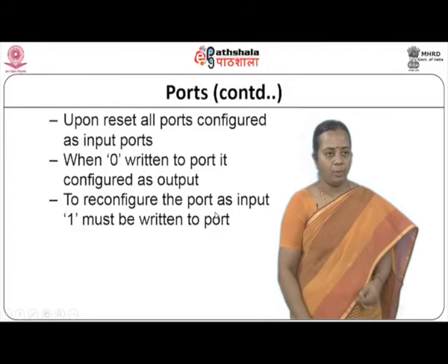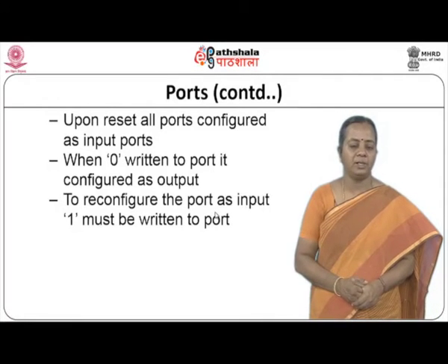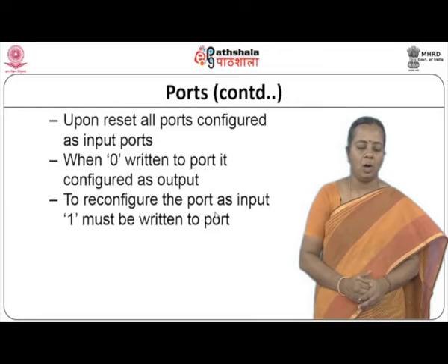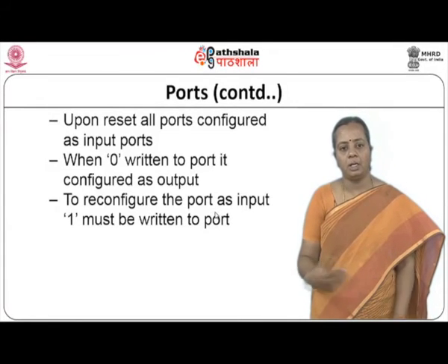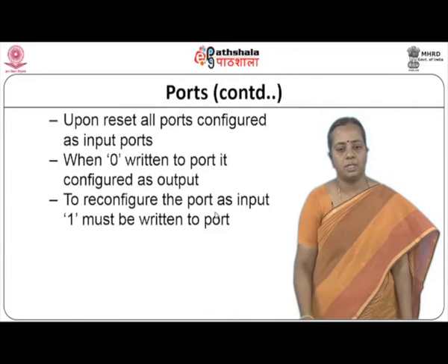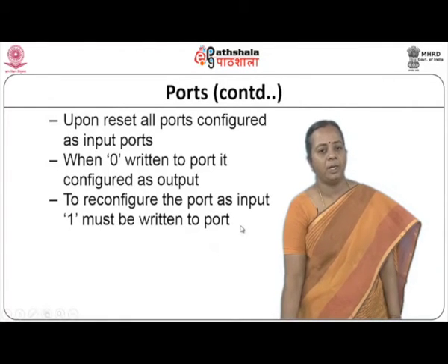So, if a particular port or pin has to be used as an input, I should always start by sending 1 to that pin or port. That declares that pin or port as an input pin or input port.